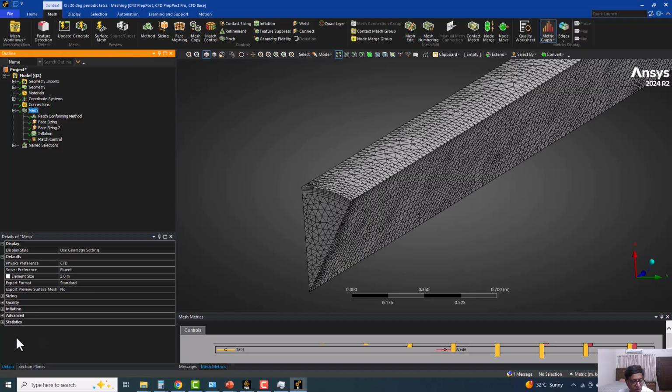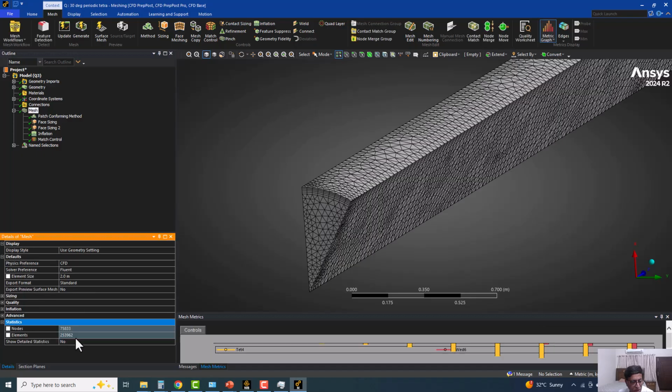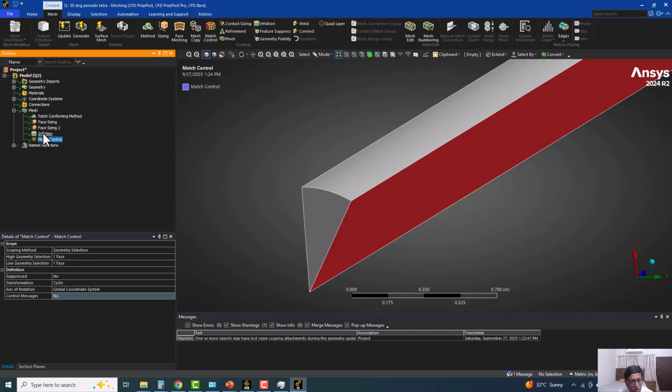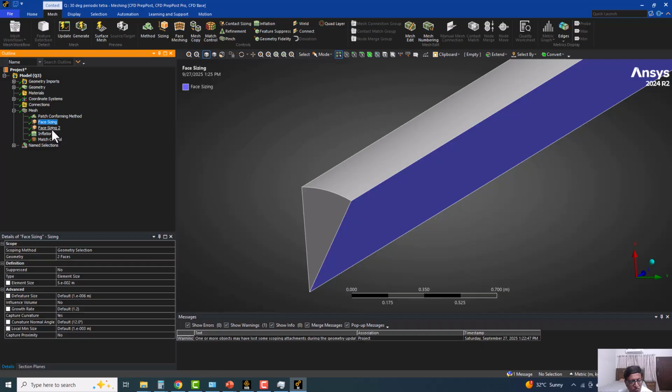And number of cells, you will be surprised to see elements are 253,000, same as a 3D mesh. So this is a problem with the 2D mesh, especially when we are getting the triangular mesh. If you go for hexa meshing, the number of cells will reduce substantially. Still, we have to make some cells here to represent the geometry and the flow properly, but I would say it's maybe 1/10 of the mesh size of this one.